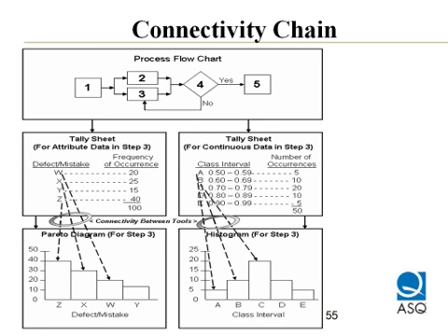Then in the bottom row, what we've got is an extension of the tally sheet for the attribute data. And as we saw earlier in the presentation, when we're dealing with attribute data, we've got defect W, defect X, defect Y, defect Z, and you can see the histogram is formed, and you can see which is the most important in terms of the greatest number of defects. And if you need to, you can always use the nested approach to further analyze each of those various types of defects or mistakes.